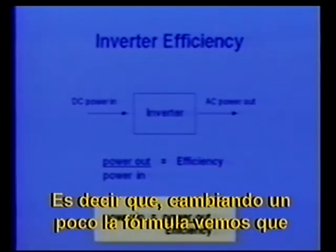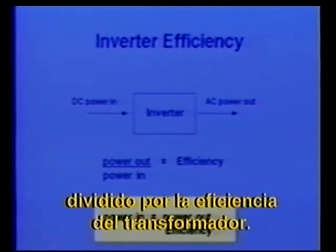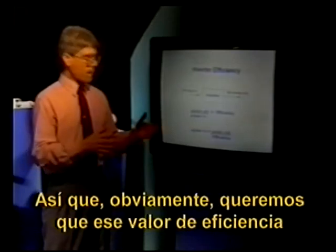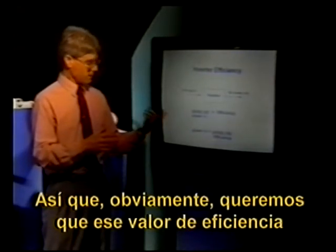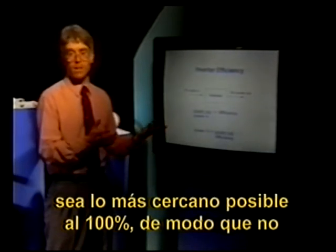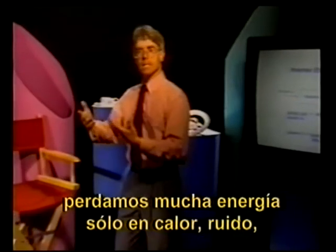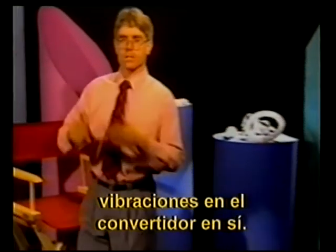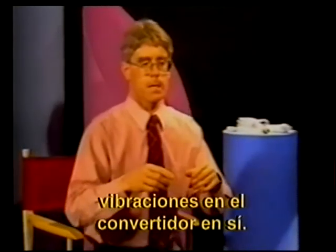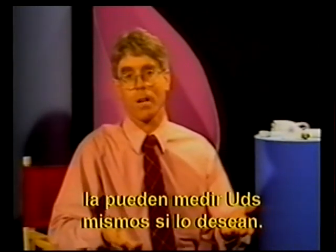So, by changing the formula a little bit, we get the DC power in is equal to the AC power out divided by the efficiency of the inverter. So obviously, we want that efficiency value to be as close to 100% as possible, so that we don't lose a lot of energy just in heat and noise, vibrations in the inverter itself. You typically read these off of manufacturer's literature. You could measure it yourself if you wanted to.